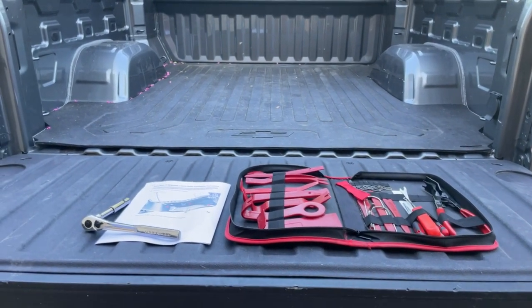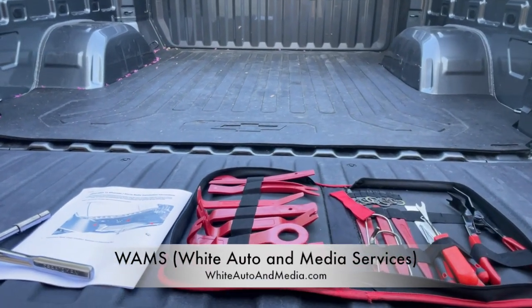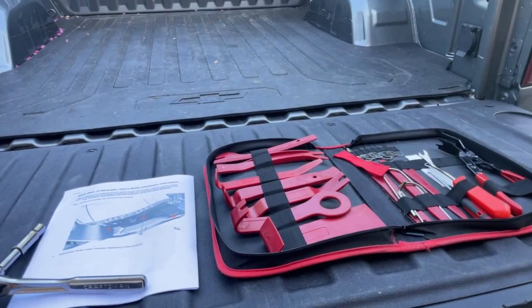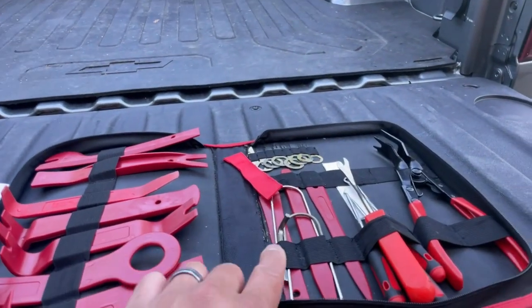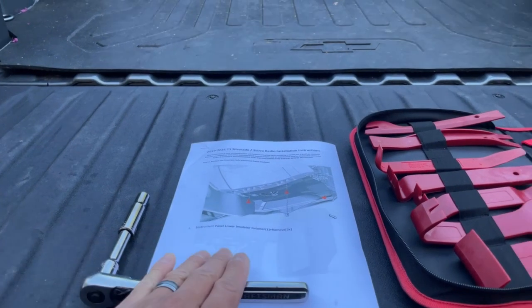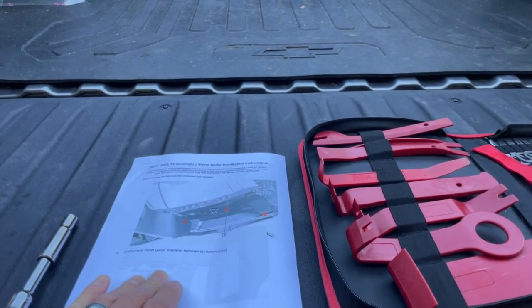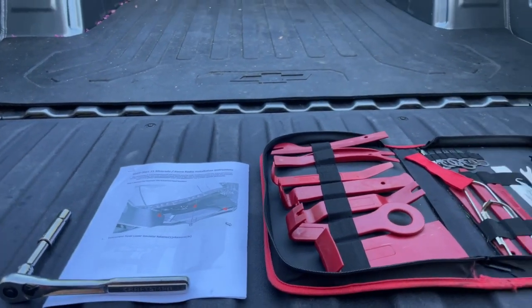I plan to send the radio module off to White Auto and Media Services for the purposes of getting factory nav enabled onto it. Some of the tools you'll need for this will be a pick tool set, something like this where you have various pick tools to get to some of the connectors, a 10mm socket, and the removal instructions. The removal instructions I actually downloaded from White Auto and Media Services website. I'll put links in the description below.